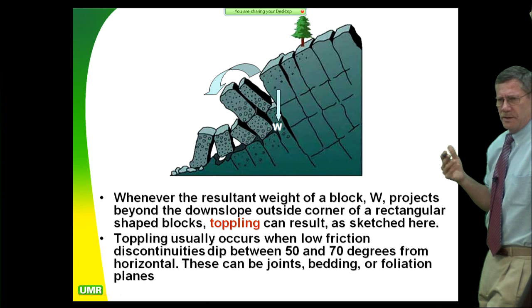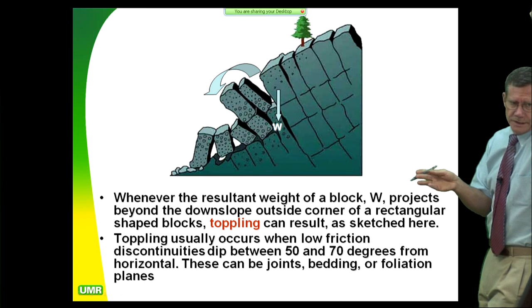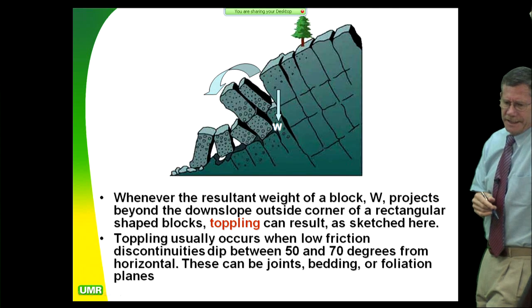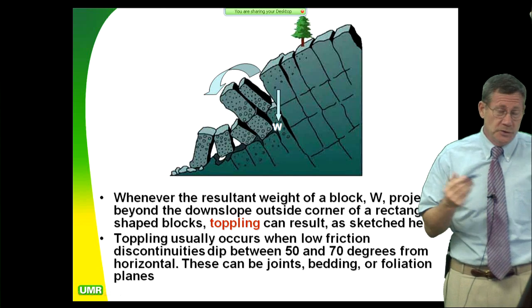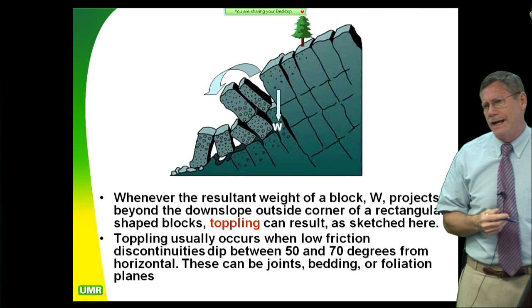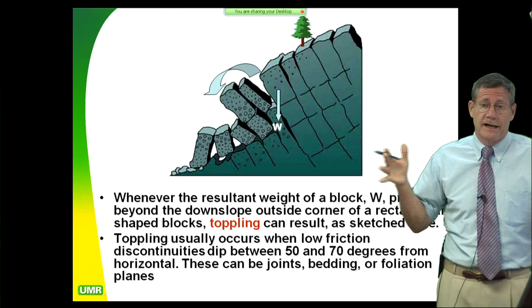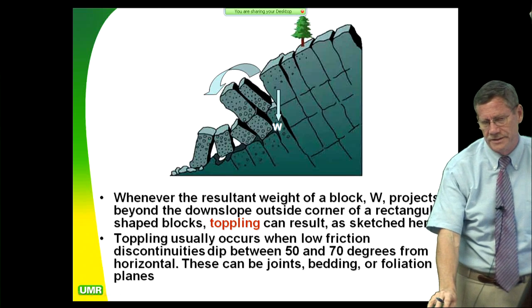What kind of rock is most susceptible to land slippage? Believe it or not, it's mica schist. Mica schist, absolutely the worst for large bedrock landslides. If we look at the Lhasa, Tibet to Kathmandu, Nepal, Friendship Highway, massive slides on that. Keep the highway closed 2/3 of the year. Most of them are in mica schist and other metamorphic rocks. These are rocks that are heavily tectonized in the Hindu Kush, but the slides are just giant wedge failures and toppling failures.